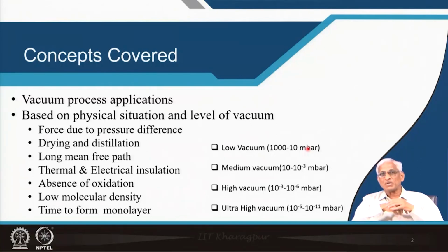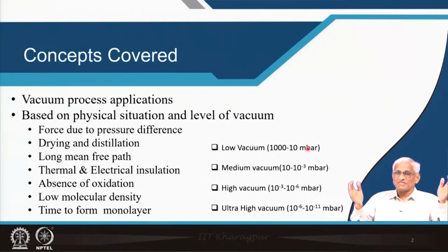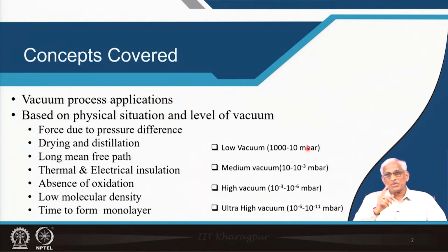Then medium vacuum, 10 to 10 power minus 3, that means 99.999% is already removed, but metallurgy applications have not started, materials applications, plasma applications, nuclear and space science, and most important electronic applications like cell phone manufacturing, computer manufacturing, they have not started at all. So, this is a beautiful concept: when you remove 99.999% of the gas from a chamber, even then most of the high tech applications have not yet started. So, it is only the removal of that last bit of that gas that is very important.